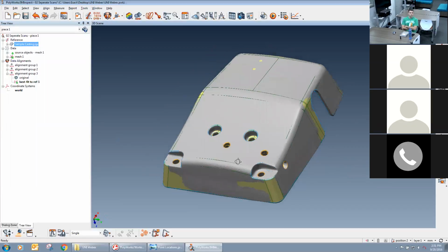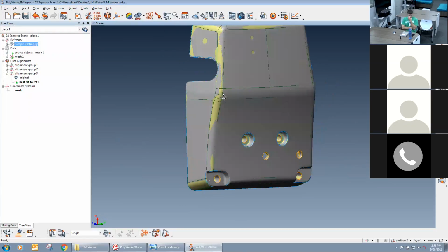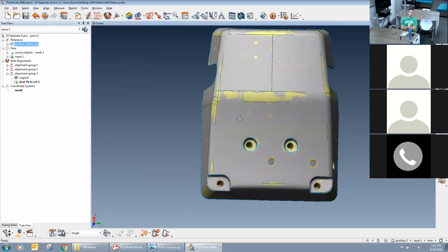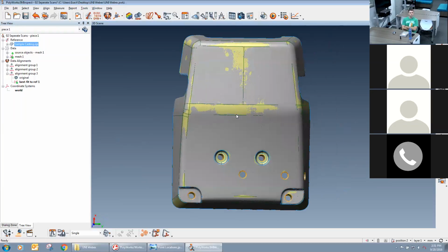So on a print with tooling points, I'll show you a couple different scenarios. One would be I have 3 A targets, 2 B targets, and 1 C target. So in order to do that, I'm going to go ahead and hide the data. Over in the tree to my left, if I middle click on the feature, so mesh 1 there, I can hide and show it.